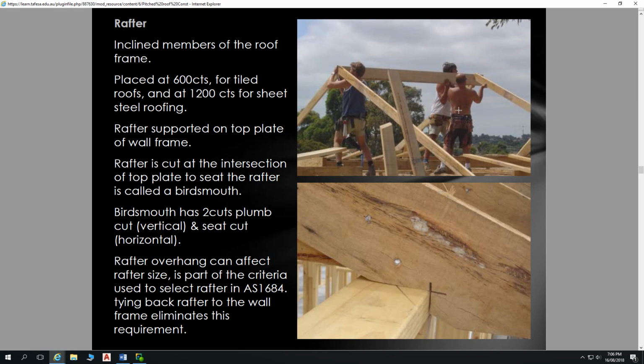Then our roof sheeting is going to go on top of that. So our roof sheeting is tied to the battens or the purlins. So that's tied down by screws or nails, or typically today screws. Then those battens or purlins are going to be fixed down to our rafters. Typically that's going to happen with type 17 bugle screws.